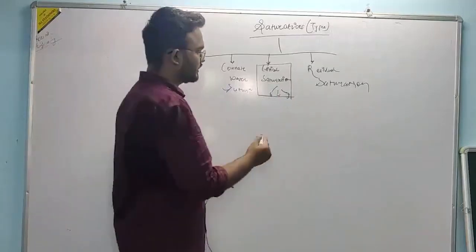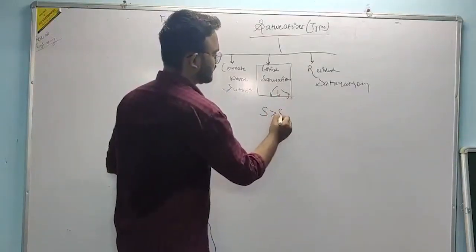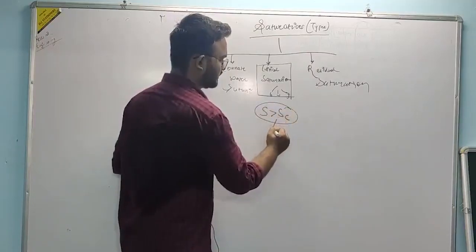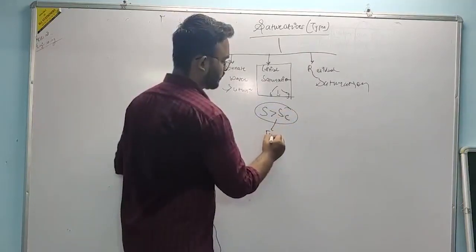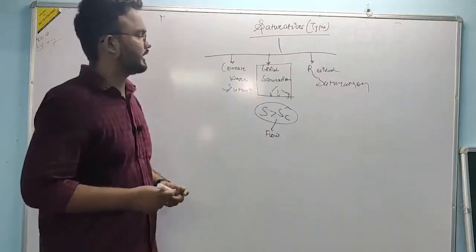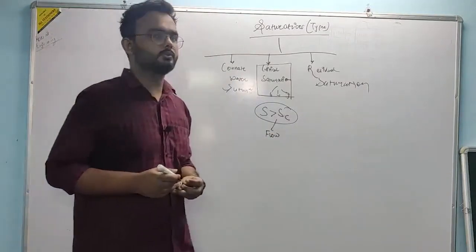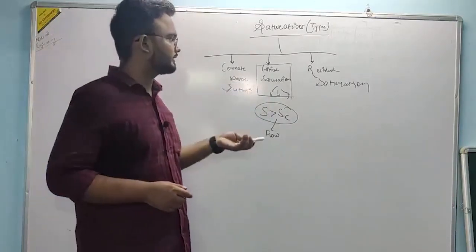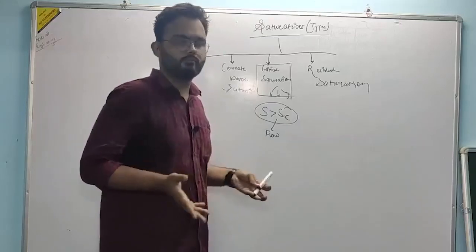A saturation which, if it gets higher than critical saturation, then you can say that the phase will flow. Otherwise it won't. So the critical saturation is a saturation which is a must for a fluid to flow. If oil is at a saturation lesser than critical saturation, oil will not flow.